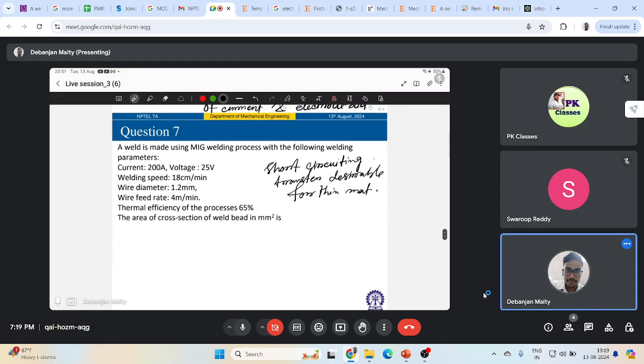So what I have talked about in terms of metal transfer: short circuit transfer is promoted by the lowest current as well as the lowest voltage. It can use CO2 shielding gas for your gas metal arc welding. Now the advancing electrode will make direct contact with the weld pool and the short circuit will cause a rapid rise in current, and big molten globes form on the tip of the electrode and then it separates. So basically, it will